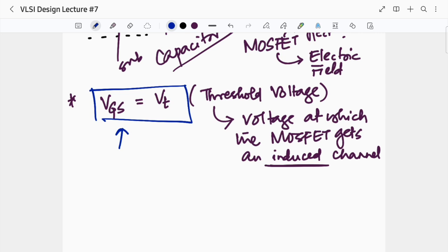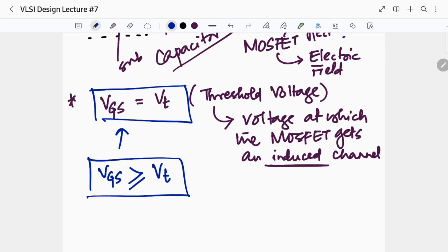So if I have to make my channel strong, a better channel, how will we do that? We keep on increasing our VGS so that it is greater than or equal to Vt. The minimum condition over here is VGS equals Vt. That will also work for us. But I want my channel to be strong. So how will we do that? By keeping on increasing VGS such that we follow this condition of VGS greater than or equal to Vt. That is how our channel will get strong.